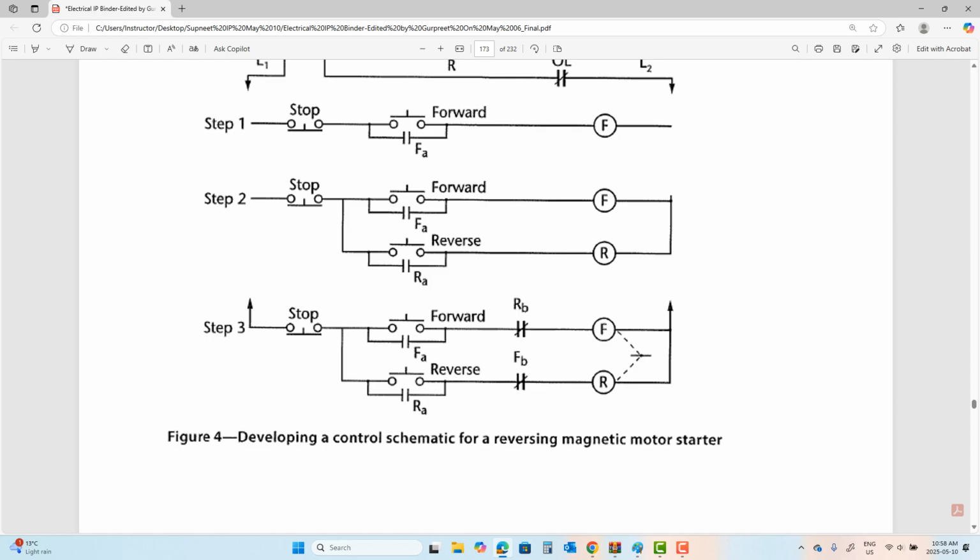This is called electrical interlocking. Electrically, the schematic is designed in a way that even if the mechanical lock breaks, electrically you cannot kill the motor. So the question in the exam is, the schematic in front of you, is it providing A, electrical interlocking, B, mechanical interlocking, C, both, D, none? What do you think? Both. There is mechanical through this dotted line. This is electrical that I just explained, so it has both.